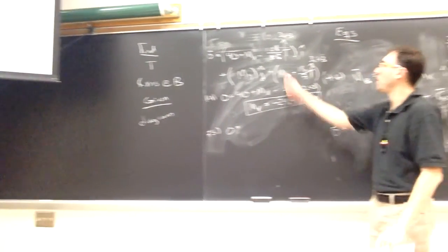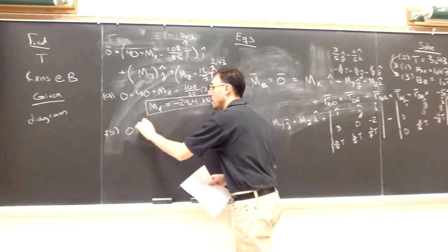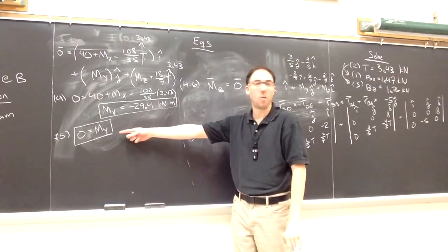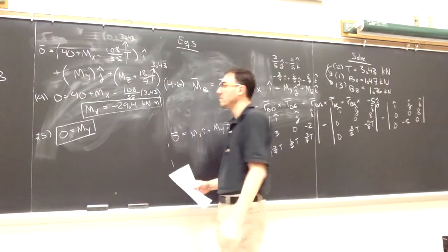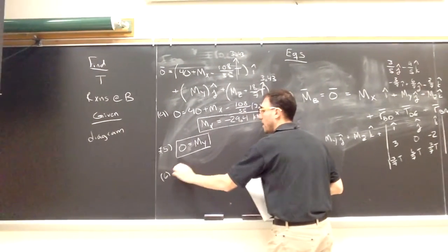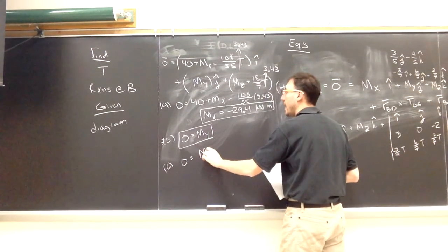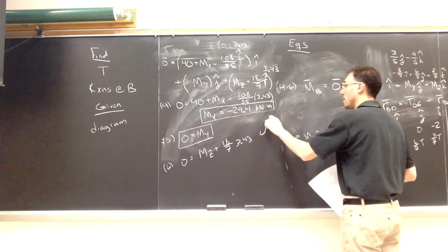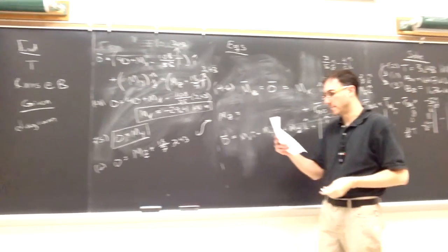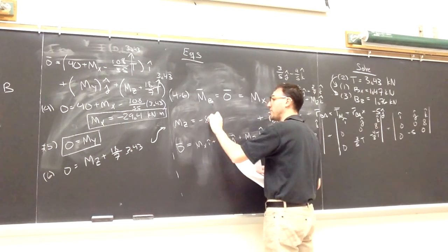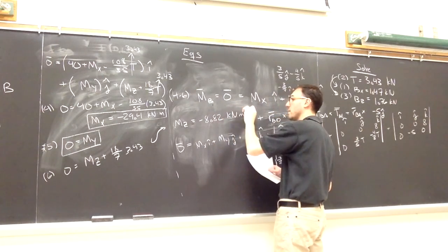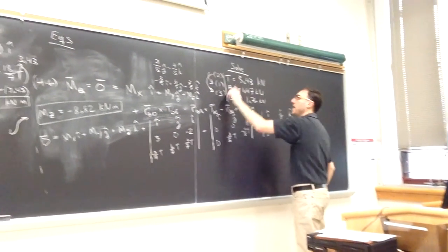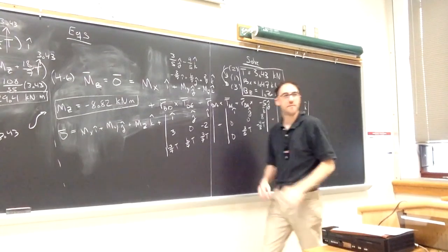I get a fifth equation. I set this coefficient equal to 0. Since the only thing in that coefficient is my, it turns out that my is 0. And finally, the coefficient in front of k, I get that mz plus 18 over 7t equals 0. Solving it then for mz, mz is a negative 8.82 kilonewton meters. Between these 3 moments and then these 3 forces, I have all of my reactions.